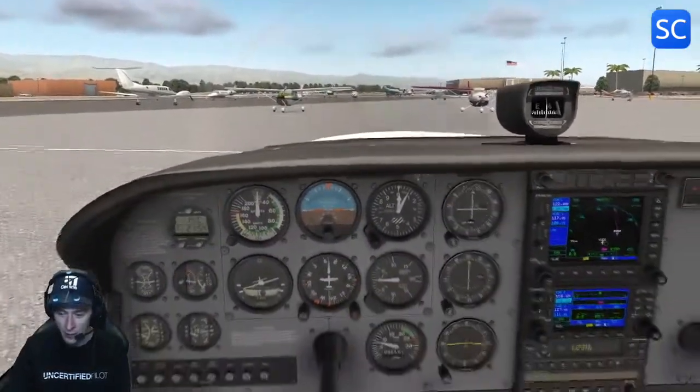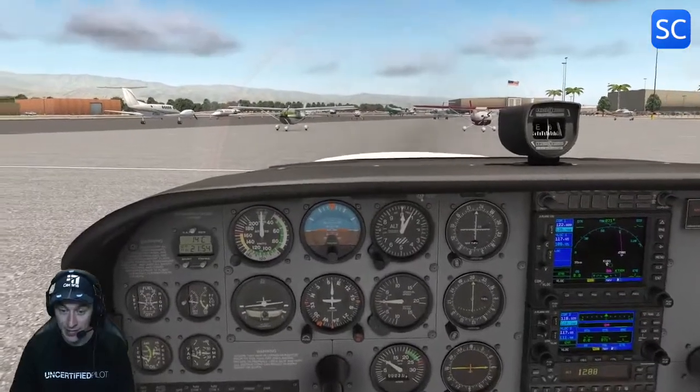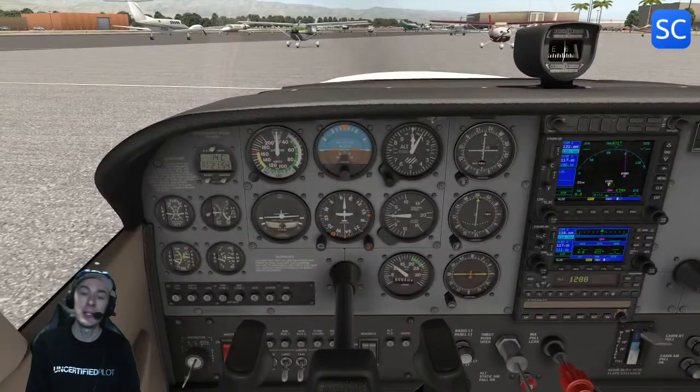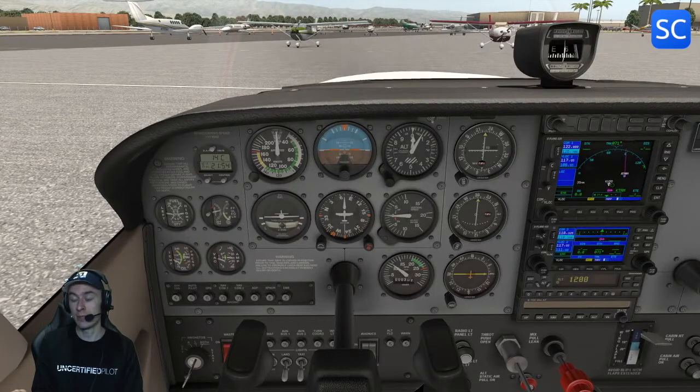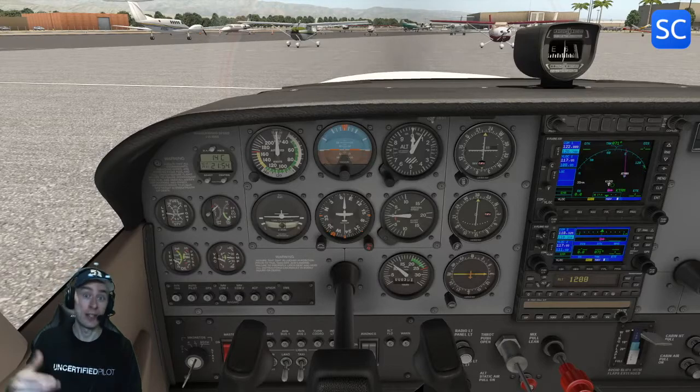Very nice. Also, in terms of taking care of your airplane, like in the real world, it's actually quite damaging to shut down your engine, but also to start it up with your avionics on, because it might lead to a power surge from the engine to your battery. Because electrical power is drawn from the engine, right?